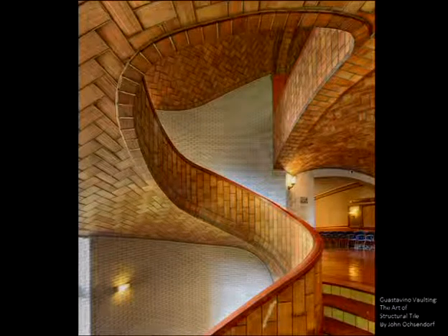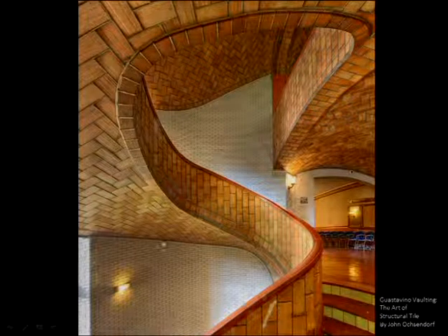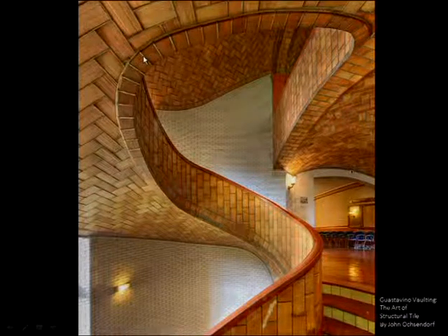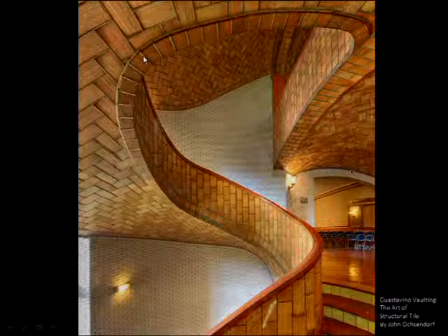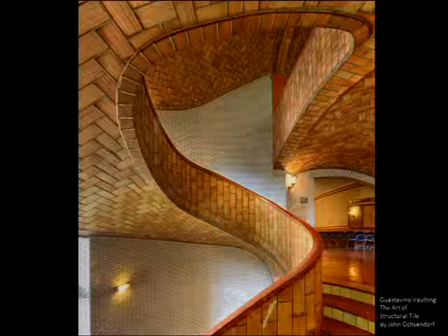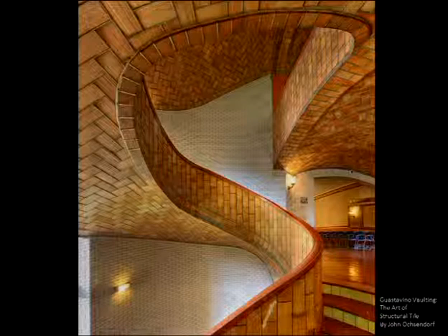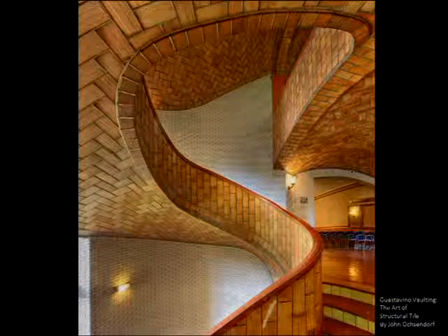This is an example of a stair done by Guastavino, and you see this is a vault. All this is an actual vault. It's a compression-only situation that he was able to get out of a geometrical operation. So he knew how to calculate the thrust line, so exactly where the compression forces go through the structure, just through a geometrical process. That is called graphic statics.